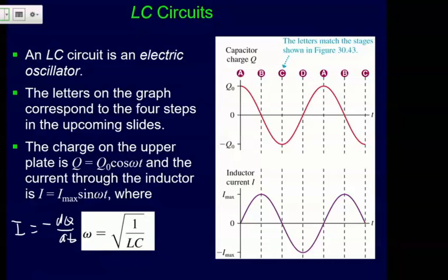And then what happens is when the charge on the capacitor is 0, when the capacitor has discharged all of its charge, which in an RC circuit would be done at that point, in a capacitor and resistor, what's happening is at that point you've got this current in the inductor, and that current can't just stop immediately. So that current keeps on going in such a way that it charges the capacitor the other way. The capacitor started with positive charges on the top, and then it'll end up with negative charges on the top as it charges itself the other way. And then basically this thing just repeats.